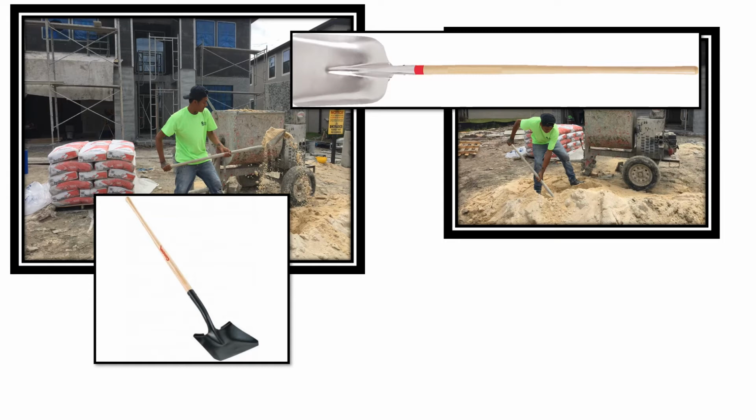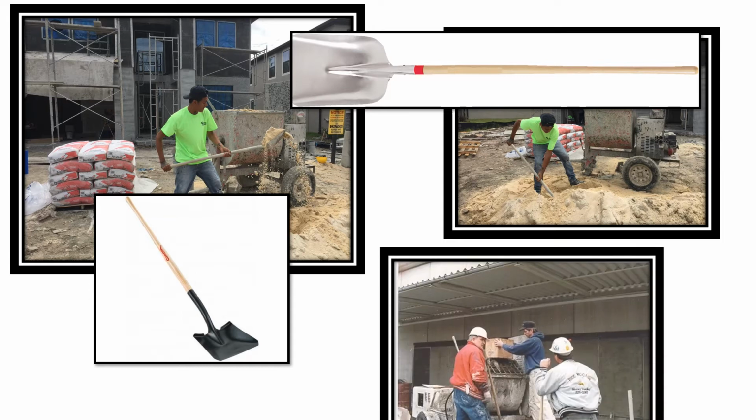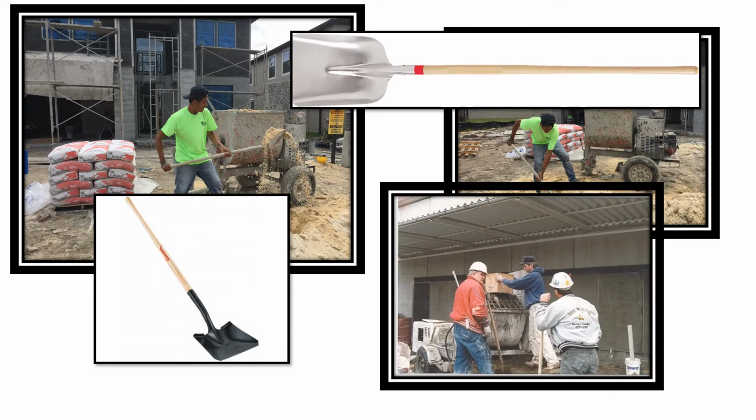The amount of sand should always follow ASTM for generic mixes and manufacturer's recommendations for concentrates or blended products. Even though sand can range in ratio from 2.5 to 5 parts per cement, some consultants may demand a more accurate measure than the shovel count. This can be done by making a 12-inch by 12-inch square box to provide a 1 cubic foot measure of sand. Once the number of shovels or scoops needed to fill the box is verified, the mixing can then be done with a shovel count.